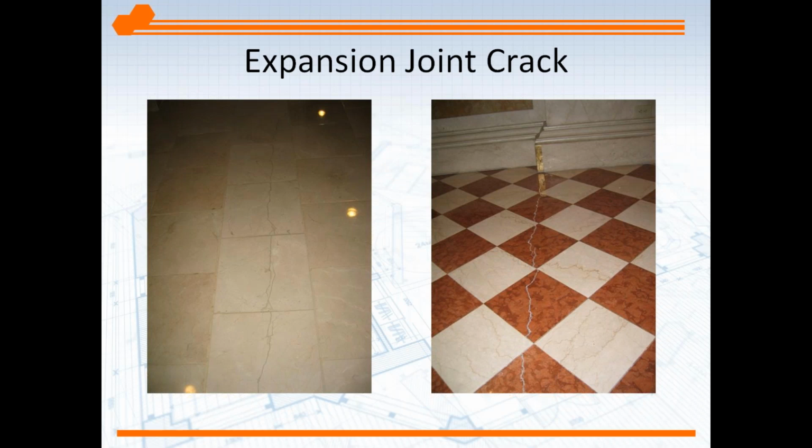And you see here just some areas where the crack is there for a reason. It's a shame. Something wasn't done in prep. Something wasn't recognized in the installation. This is an extreme case. I see many of these in much more subtle cracks and whatnot, but this is where the mortar was not placed underneath the tile, or maybe shrunk away from the tile, and then a lift or something was driven over this, because like I say, it's pretty extreme.